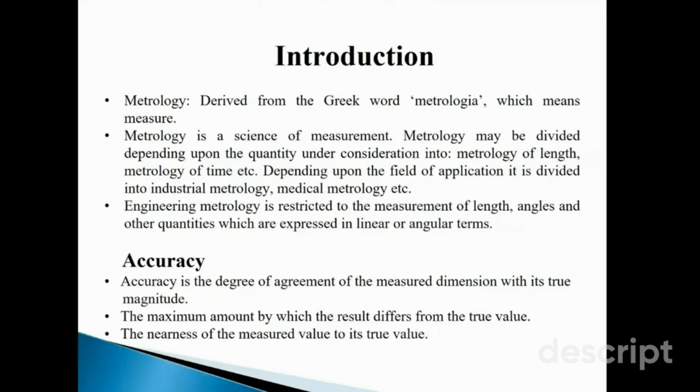It can be an error in the tool, or it can be an error in the operator's skill itself. Due to this error, there is a problem in manufacturing the product to the actual size. For that purpose, what is defined? You define the limits. There is an upper limit and a lower limit, and in this particular range your size is acceptable. I gave you an example: if you want to wear spectacles, or suppose a shirt, then you see the size range.